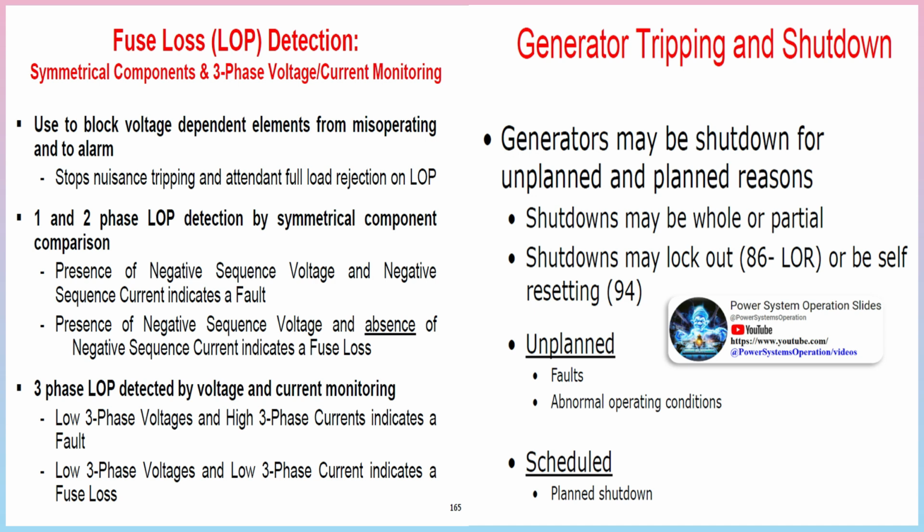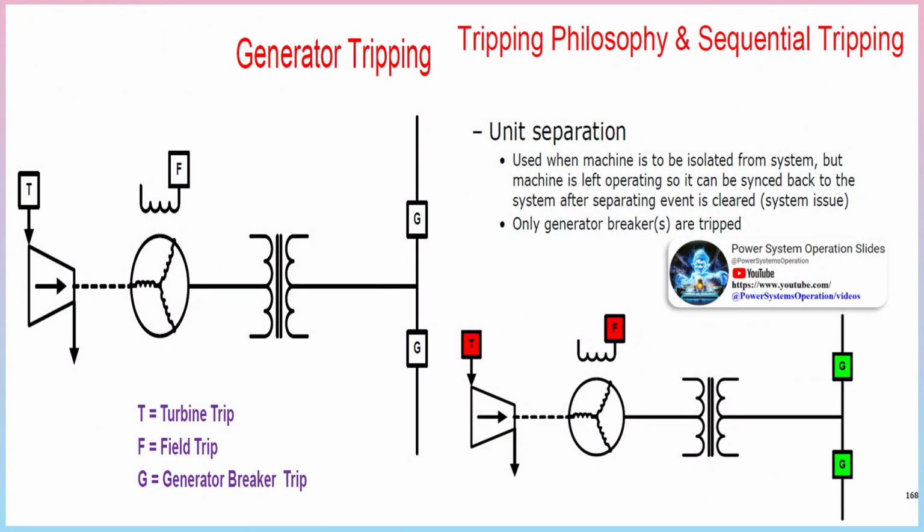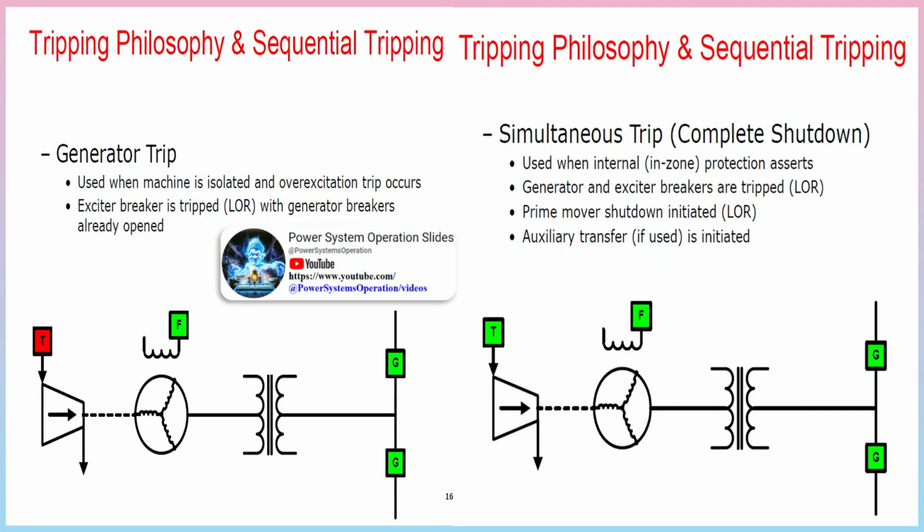Protection against difference in expansion between rotating and stationary parts. During the running up period, the rate of heating of the rotor differs from that of the casing, due to the difference in mass. As a result, the rotor expands at a different rate to the casing, and it is necessary to overcome this unequal expansion. To this end, provision is made on the larger machines for independent supplies of steam to be sent to certain joints on the casing. It is desirable, therefore, to provide a means of measuring the axial expansion to assist the operator to feed the steam to the correct points, and also to provide indication of any dangerous expansion. The shaft axial expansion detector is basically similar to the equipment described for rotor distortion, except that the detector magnets are fixed to the turbine casing.